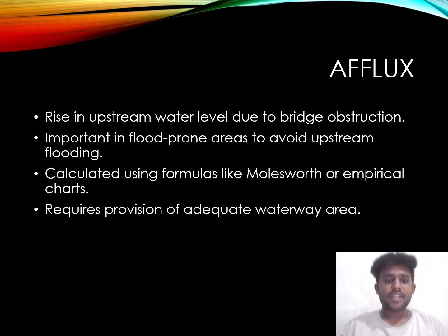Afflux, rise in water stream level due to bridge obstructions. Importance in flood-prone areas to avoid upstream flooding, calculated using formulas like Molesworth or empirical charts, requires provision of adequate waterway area.